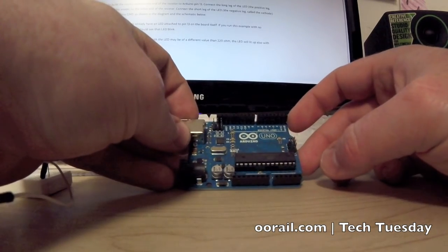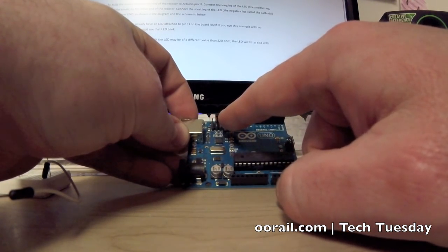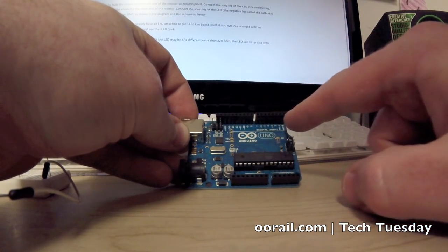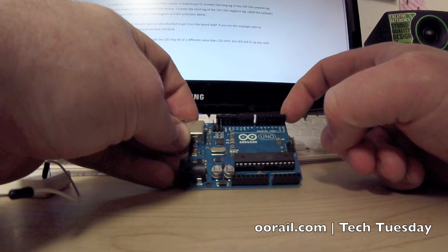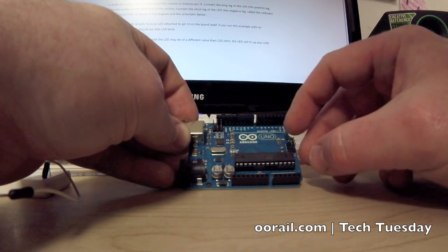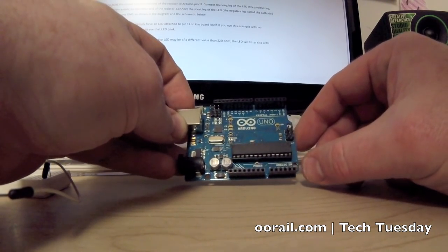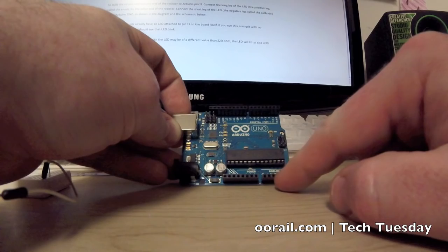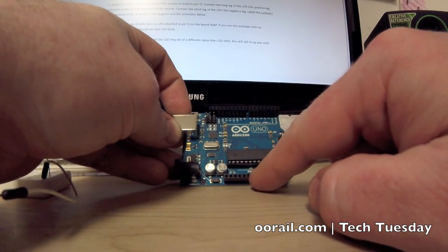You have your pins here, so down along the top you've got ground and a bunch of digital pins. The ones from pin 7 to pin 0, I believe, are the pulse width modulation ones, and that'll become important in future projects. And then down here we have the analog inputs, and we have some power outputs as well.